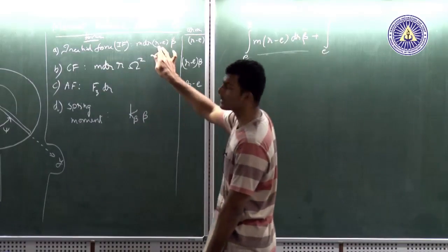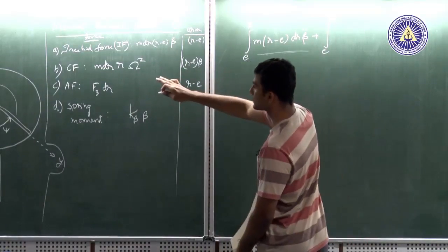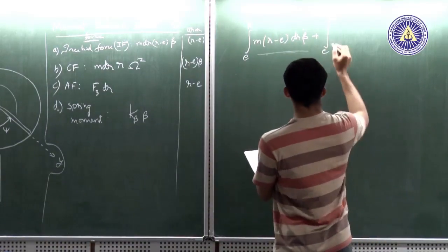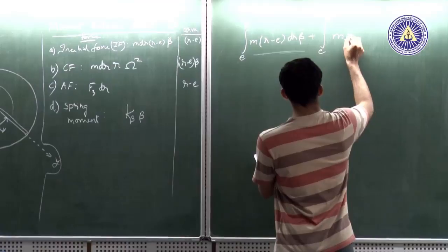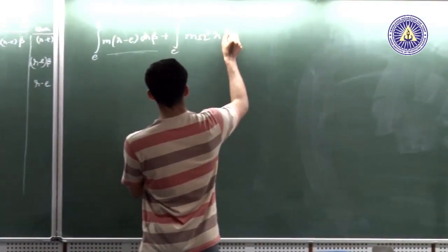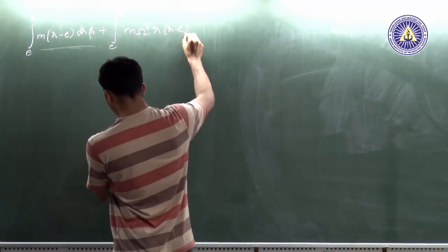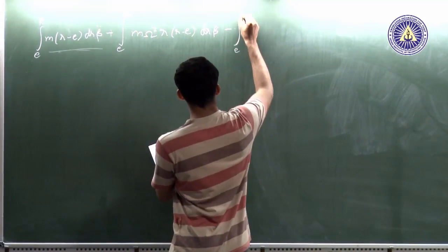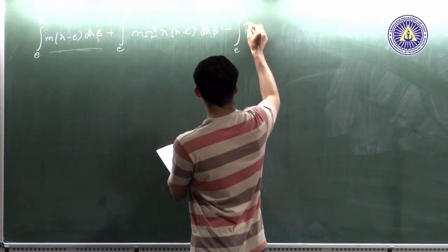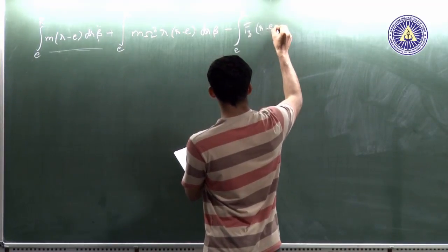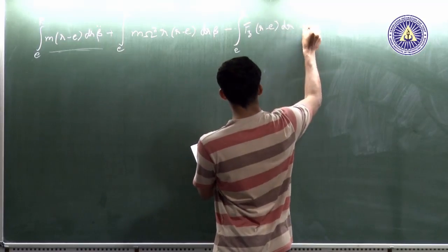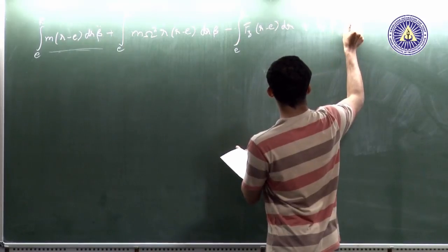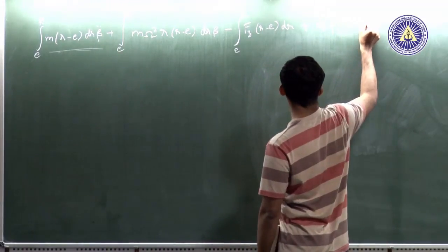Inertial force. Okay, now I am going to do it for centrifugal and the remaining forces and the spring moment. Omega square (r minus e) dr times (beta minus e to r), F_z (r minus e) dr plus k_beta beta, and that should be equal to 0.